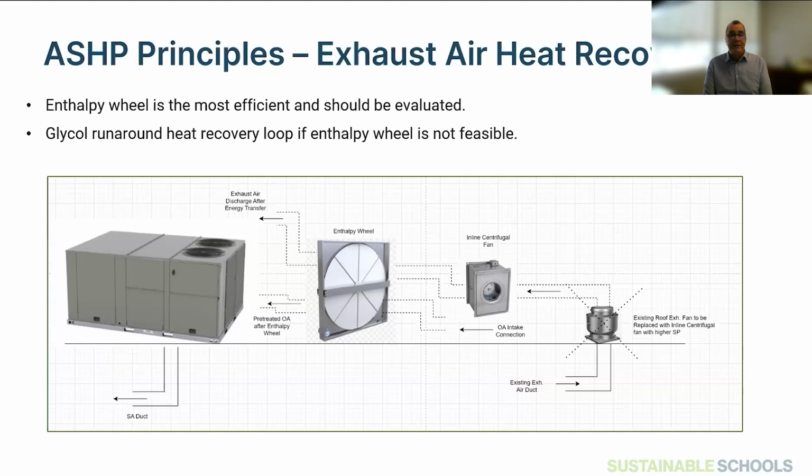We only had really 1 year of runtime on 2 of them, so it's difficult to compare right across the system. But we've noticed a reduction of 2/3 of our gas consumption compared to a similar design school that was built in 2019 without the heat pump technology and with the boiler in the building. So it's a significant amount. Now we do see an increase in electrical consumption, so the cost is almost revenue neutral. We don't see a huge difference. The money we're saving in gas is going towards the money we're spending in electricity.